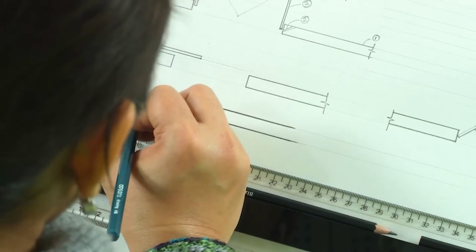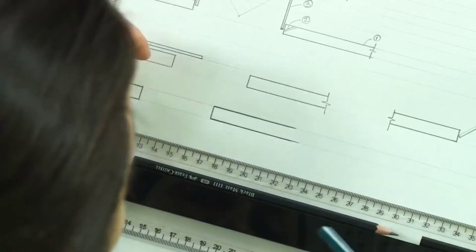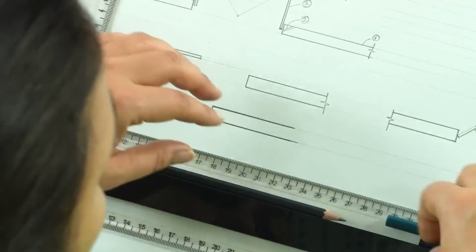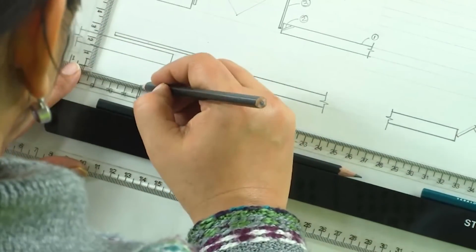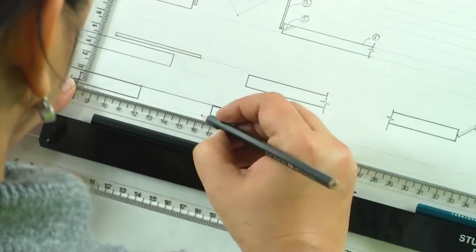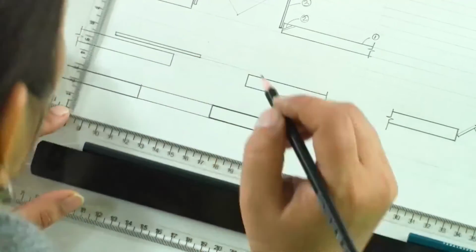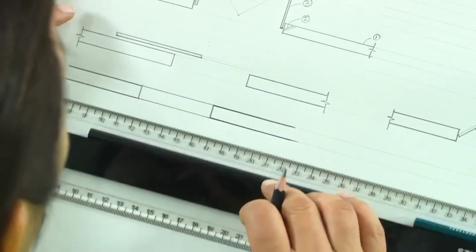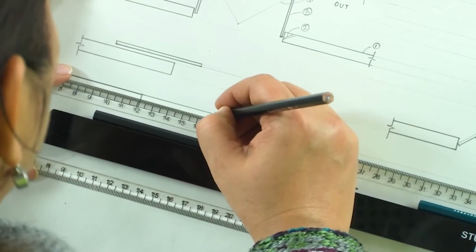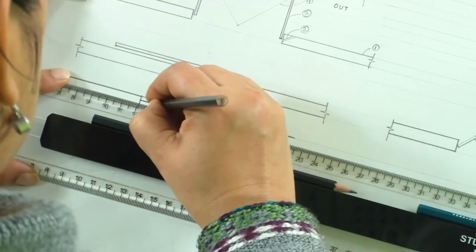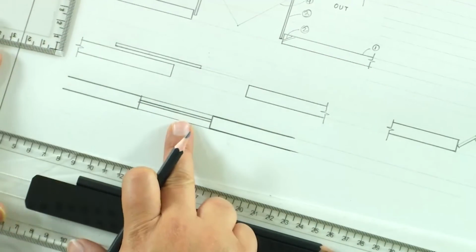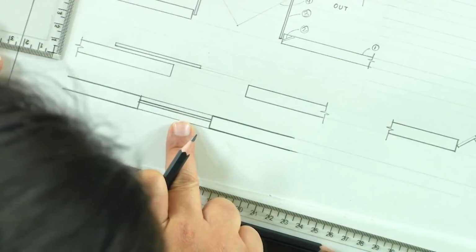Now, there is a window sill which is seen here. So, this window sill is going to be dark but thin. So, we have this window sill which is dark but it is thin, and we have a glass which is cut in section. So, that is again dark but thin. So, that is the representation for a window.